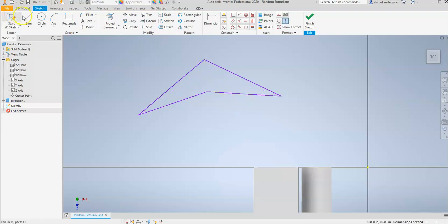And so real quick, let's click on our line tool again. This time when you put your line tool down, when you click, I want you to hold your click before you drag, and I want you to see what happens. You can see if I hold the click as I drag, if I don't let go when I drag the second line, it creates some arc. And that might be beneficial if I want it, but if I don't want it, you can see how it can cause problems. And so this is why it's important to let go of click whenever you drag.